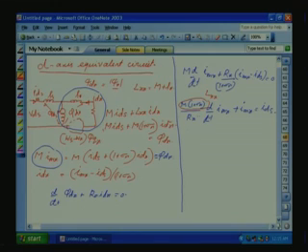So, LRR by RR is the rotor time constant. Okay, rotor time constant, that we can take as TR into d by dt IMR plus IMR is equal to ISD. So, if you see here, IMR is equal to ISD when the flux is constant, that is when TR d by dt IMR is equal to 0.